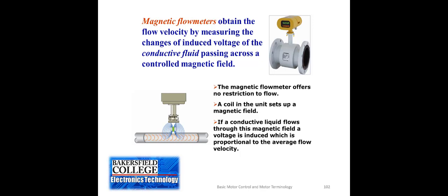So more flow rate means more voltage being generated. There is no physical device, there's nothing in this sensor or this flow meter that is in the path of the liquid. And that makes it really good because it doesn't restrict flow. There's nothing mechanical to wear out. It's all electronic. And as you could imagine, these are very expensive compared to other sensors that measure flow rate.